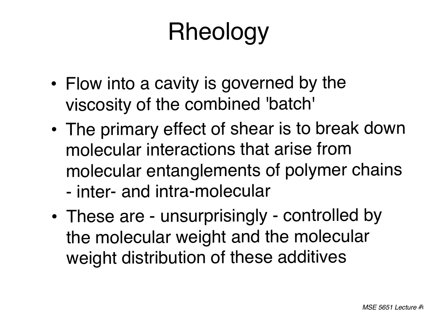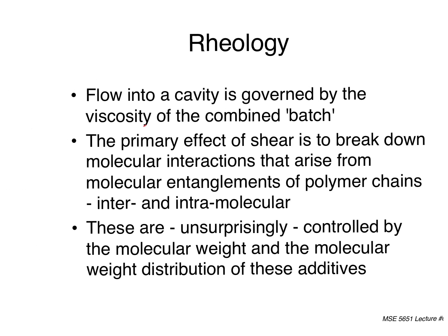And so flow into these cavities is governed by the viscosity. And we all know what viscosity is, right? Sometimes people aren't properly oriented. This table is a very high viscosity. Air is a very low viscosity, okay? Make sure I get that. Some people flip that around for some reason. And when we talk about flowing into these cavities, you've seen the shape you're creating, but there's a gate that goes into that cavity, and that gate's pretty tiny. It needs to be tiny. And so viscosity governs how easily that flow can go in through that tiny little gate.